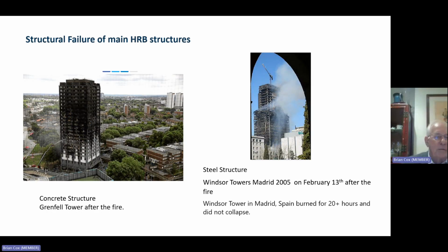If we talk about structural failure of the main structure, then we know that Grenfell Tower after the fire still stands there quite proudly as a good structure. And in Madrid in 2005, Windsor Towers building caught fire and had a terrible fire. It burned for nearly 20 hours, more than 20 hours, I think. But afterwards, the steel structure, this was a steel building, still stood there untouched.